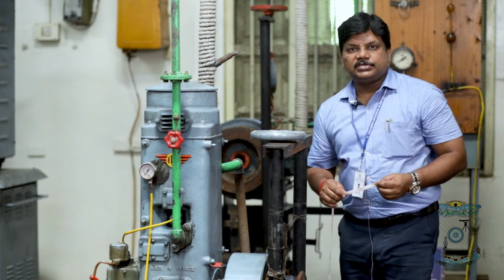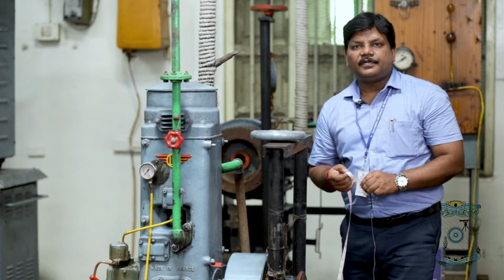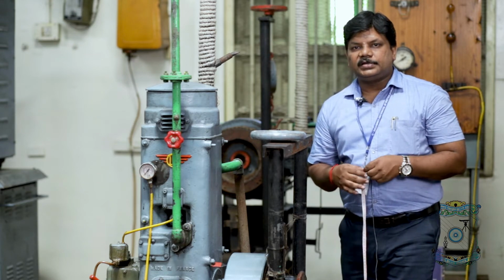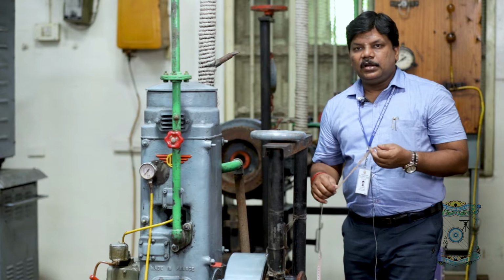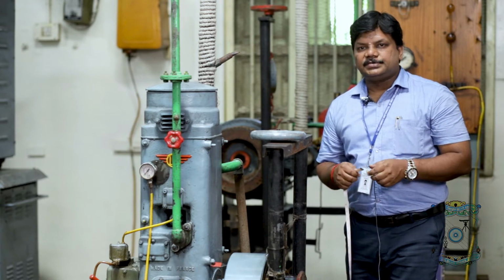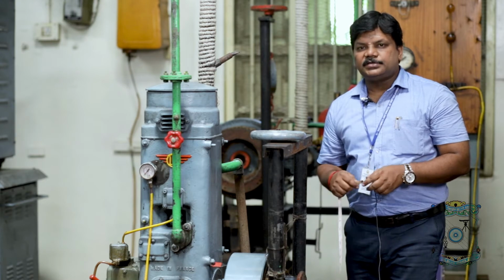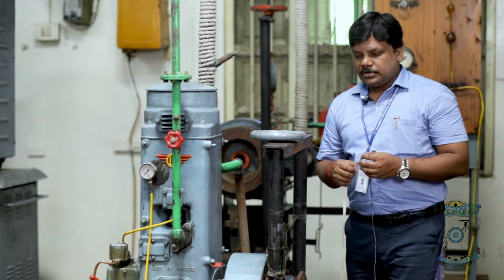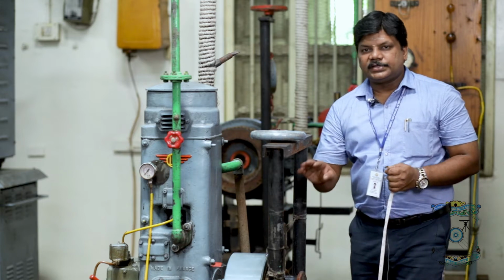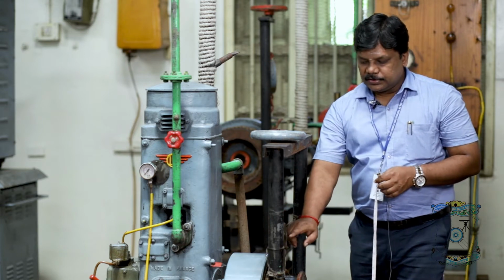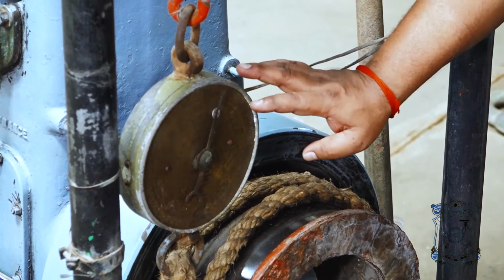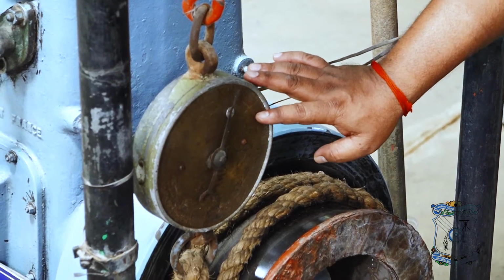And if you measure these two, you have to find the value of capital R and small r, and if you add these two, you will get the effective radius. With the help of that, you can find the value of the maximum load. Once you find the maximum load, you can go for 75% of the maximum load, kept as constant. Here in this engine, 75% of the maximum load is around 21.